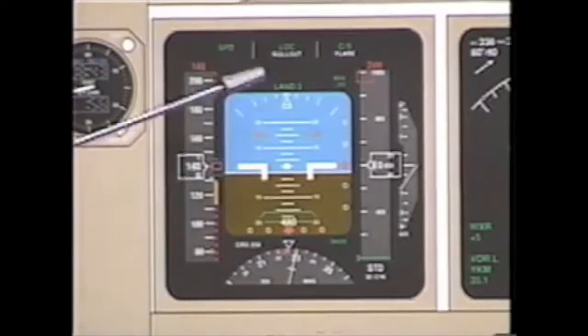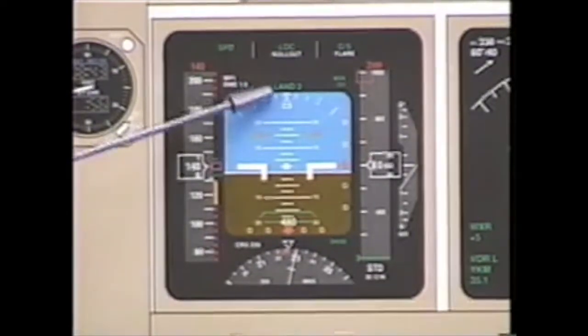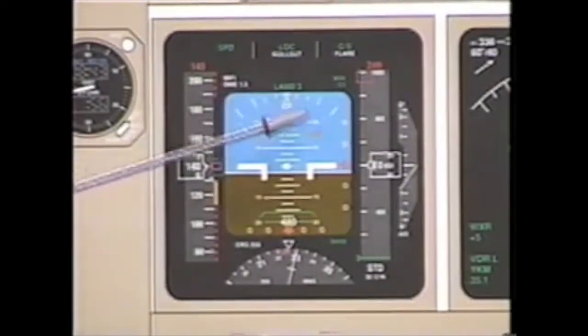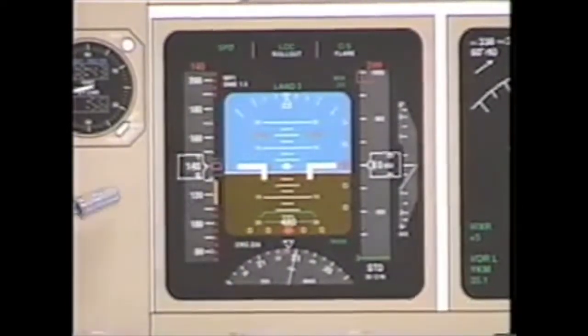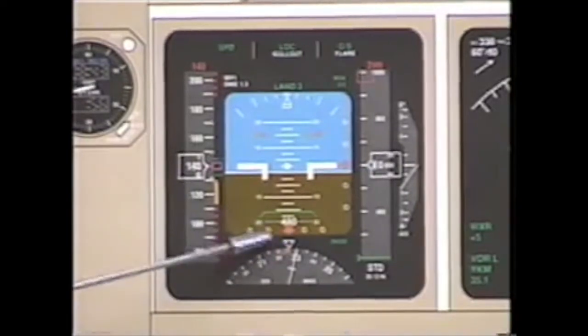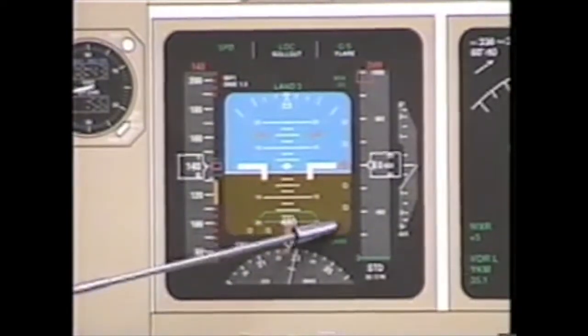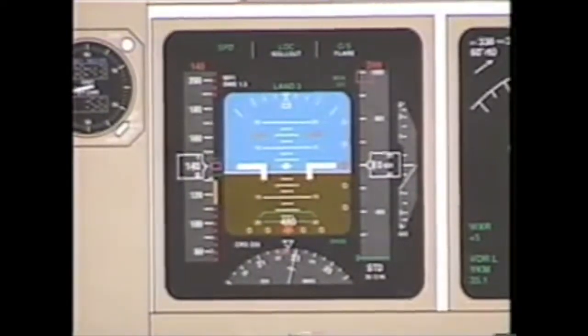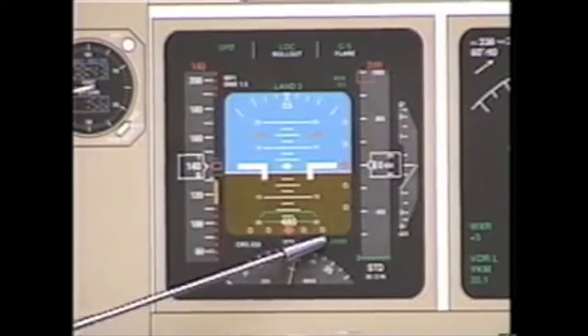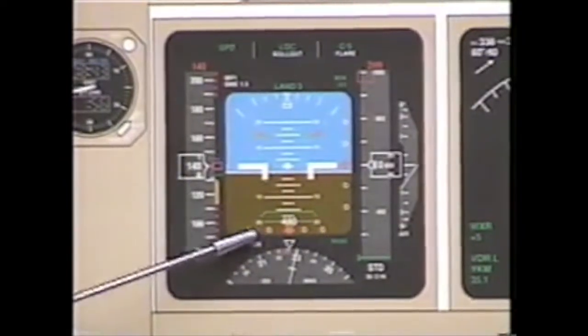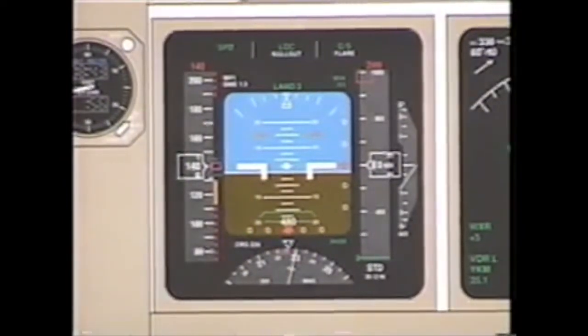Keep in mind, whenever the autopilot is shooting the approach, be it single autopilot or multiple autopilots, the autopilot will use the expanded localizer scale. This indication is incorrect in the fact that you've got your normal localizer scale, which is what you would see displayed if you were hand flying the ILS. Whenever the autopilot shoots the approach, it's the expanded localizer, so we should have 1 box to the right and 1 box to the left, which is the half scale or expanded.